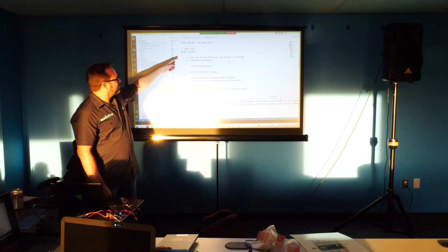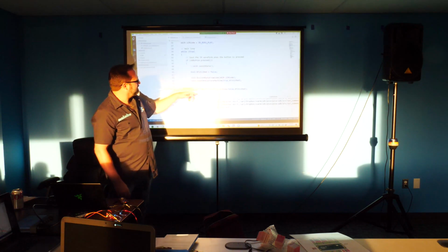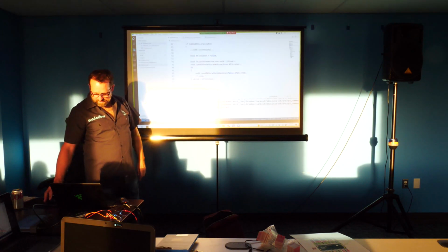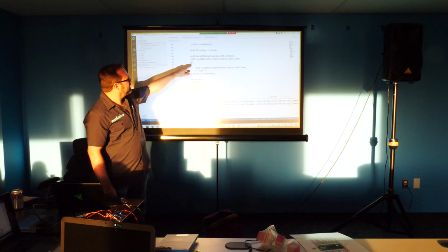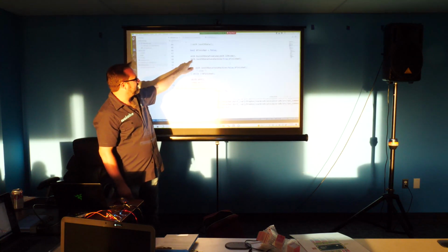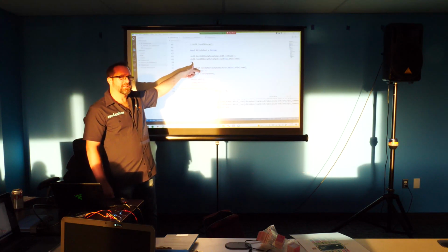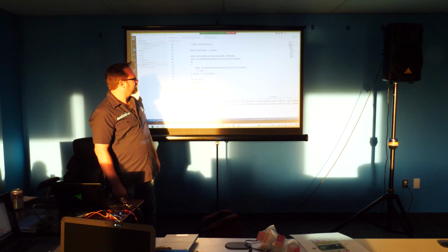This loop is very simple. It waits for the button to be pressed. Then it's going to build the IR data from the code, and then it's going to send the IR data in what we call a state machine. I'll explain what that is.